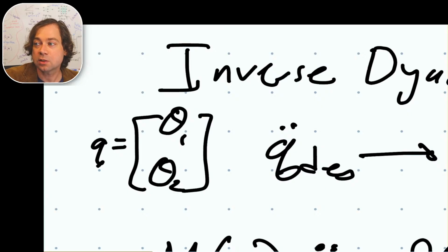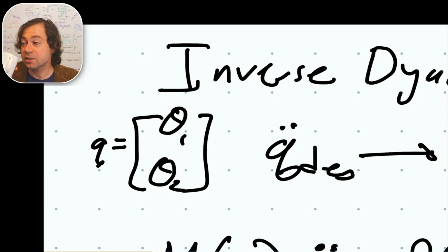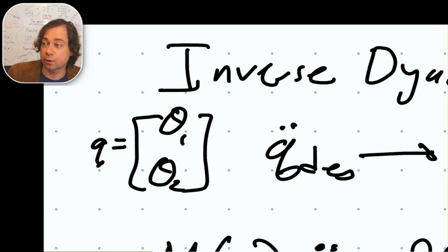Some people call this gravity compensation, because it's compensating for gravity. Even though it's under gravity, we apply torques that prevent it from accelerating. Isn't that neat? I think it's neat. I think it's super cool. All right, so now we have a new script, sim inverse dynamics.